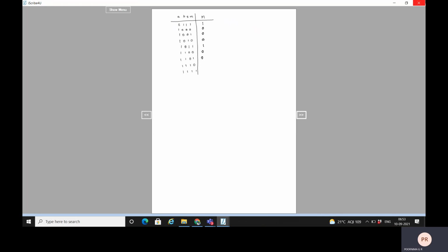So here in the next combination, two operators exist, the switch is closed, material is not there, so therefore the motor should not turn on. The last combination of the truth table, if you look at, the minimal requirement for an operator to exist at the conveyor belt is 1, but both the operators are available. Material is available, the switch is closed, so therefore the motor should be turned on.